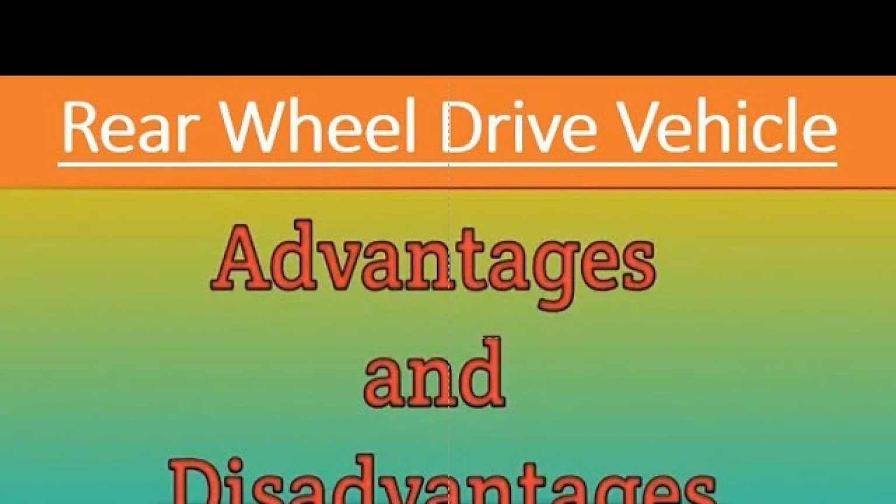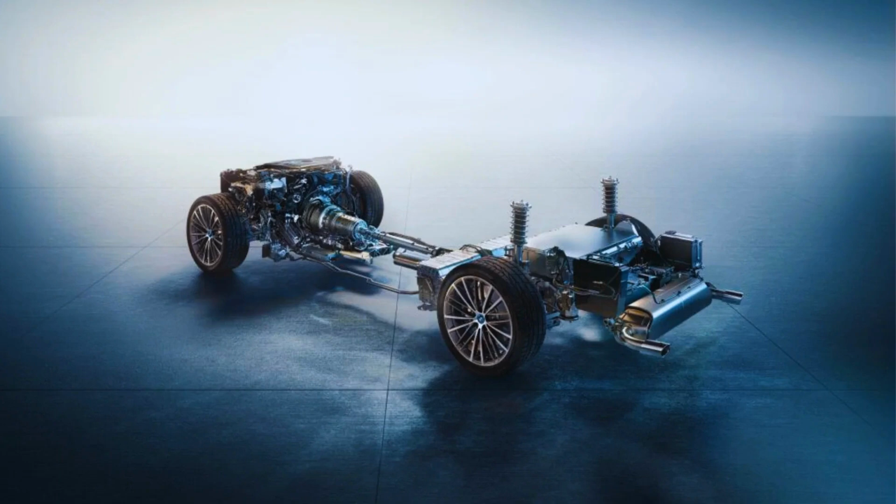Failure of the cardan leads to vibrations and knocks when starting to move. The rear differential requires periodic oil changes and, in some vehicles, adjustment. Leaky oil seals may lead to loss of transmission fluid. Friction, when dry, very quickly puts the differential out of operation. Fortunately for owners of foreign cars, these features are characteristic to a greater extent of domestic cars.